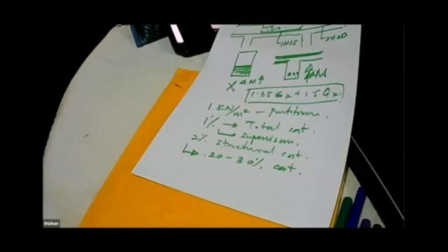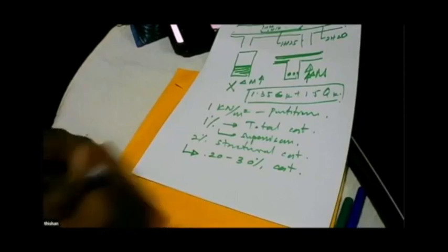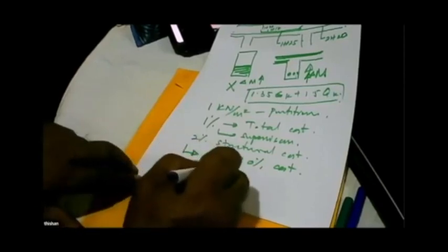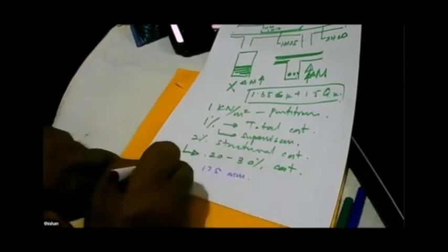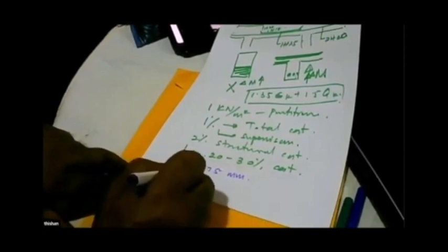Okay, sir. And sir, what can we do to take these value engineering tips to practicing engineers? I mean, from this lecture series. Now, actually, one by one I'm going to disclose a different way of thinking about structures. That different way of thinking is the one that value engineers use. So for a value engineer, a slab cannot be just 150 or 170 millimeters. It can be anything like 130, 140, 150. And he will try his best to go for 130.